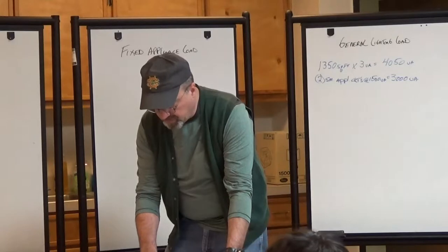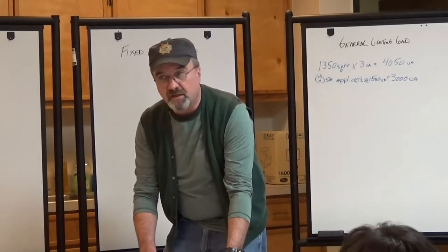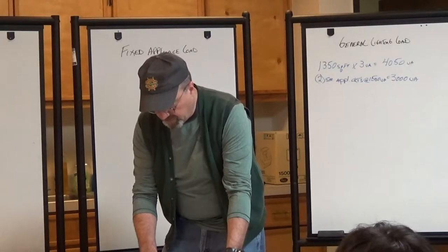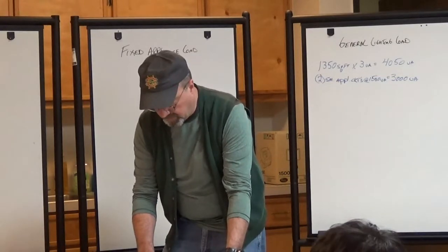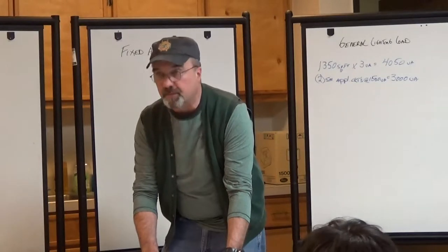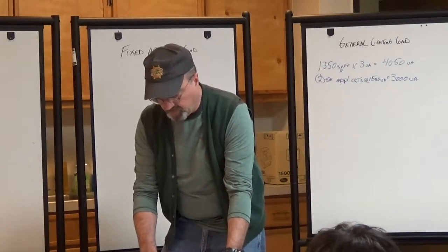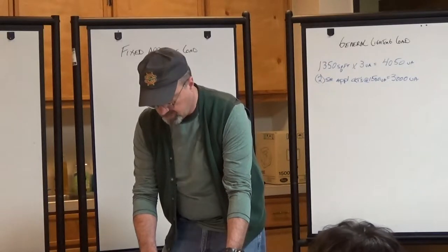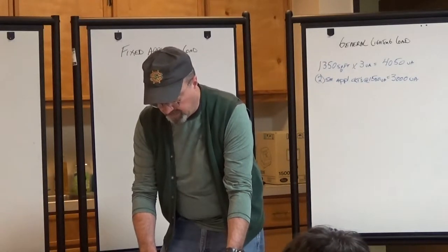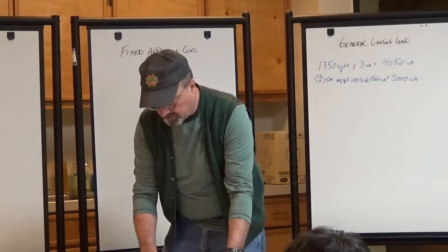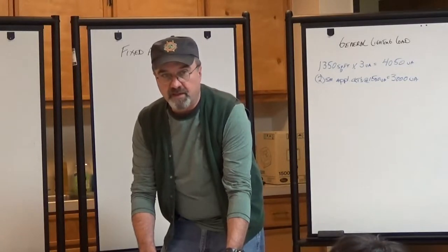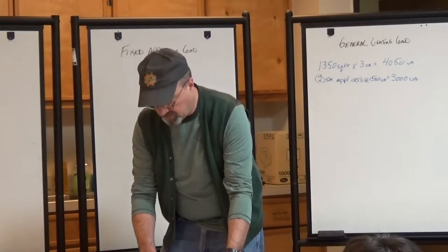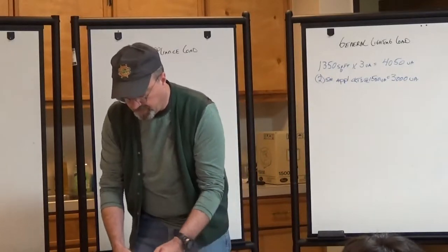It says the laundry circuit load, a load of not less than 1500 VA shall be included in each 2-wire laundry branch circuit installed as covered by 210.11(C)(2) that we just read. This load shall be permitted to be included with the general lighting load and subject to the demand factors provided in Table 220.42. So we can add the laundry circuit to the general lighting load, and we apply a 1500 VA rating to that load demand.